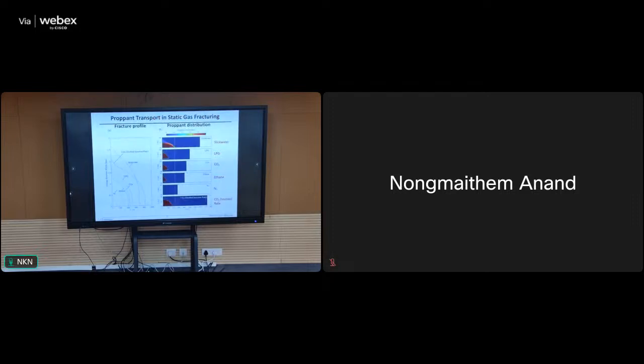But one key issue in driving these fractures using a variety of different fluids is not only the efficiency of the fracturing that can result in terms of the length of extension, but also how capable you are of propagating proppant along the length of the fracture to act as a bridging agent and to retain the permeability that you've created. If you compare slick water, LPG, CO2, reusing ethane, which you recover from the reservoir, or fracturing with nitrogen, you can see that in each of these cases, the fracture lengths diminish, even though the complexity might be elevated, and the ability to carry proppant along the fracture is also diminished in the case of the lighter gases.